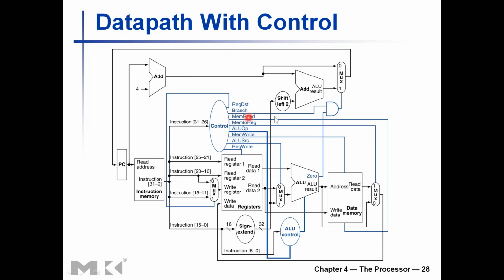So this signal will be set to high, or logic value 1, if your instruction is a load instruction, if you are reading from the data memory. That is the idea. Remember the write enable signals used in registers and memory, write enable or read enable signals. That is one such control signal. And very similar to that, the mem to reg signal, somewhat related to that.